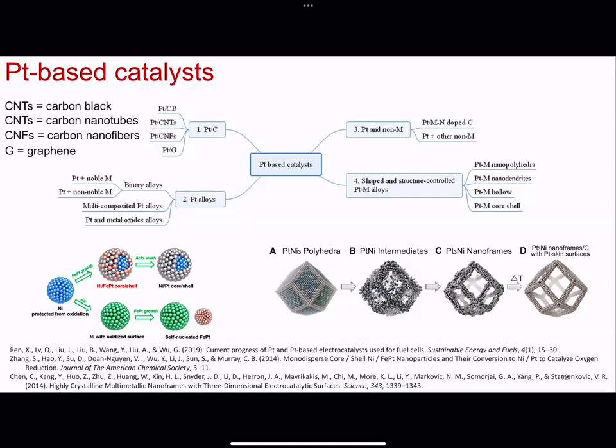Because then what you have is created a gradient, where let's say you have nickel on the inside and platinum on the outside. At the interface of platinum and nickel, or iron and platinum, or some cheaper metal, you're going to have an interface where you sort of have an alloy. And then the alloy says, well, energetically I prefer to be this alloy. So then you have movements. These are mobile atoms, so you'll have processes called Ostwald ripening. You have different sizes of structures. You also can have the Kirkendall effect,